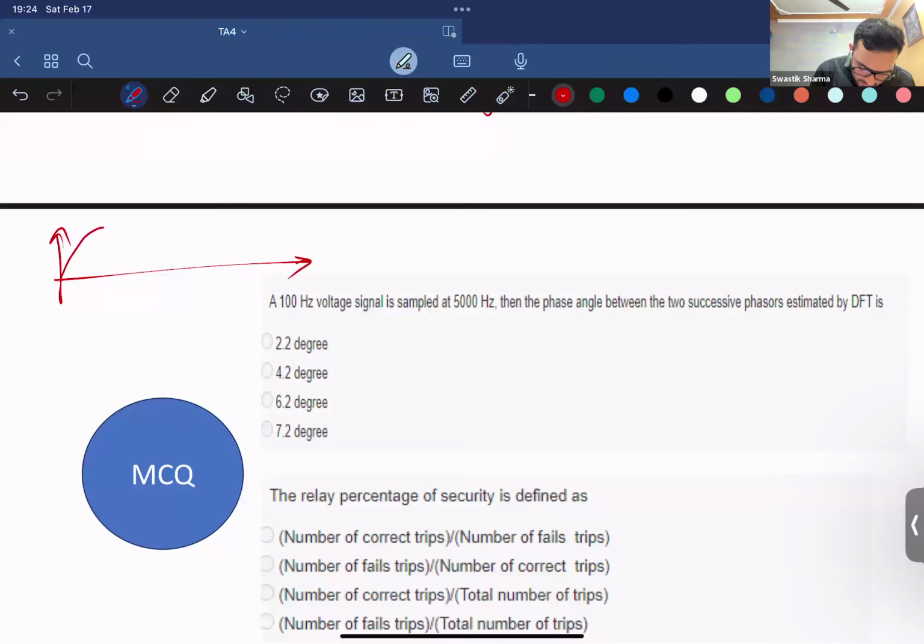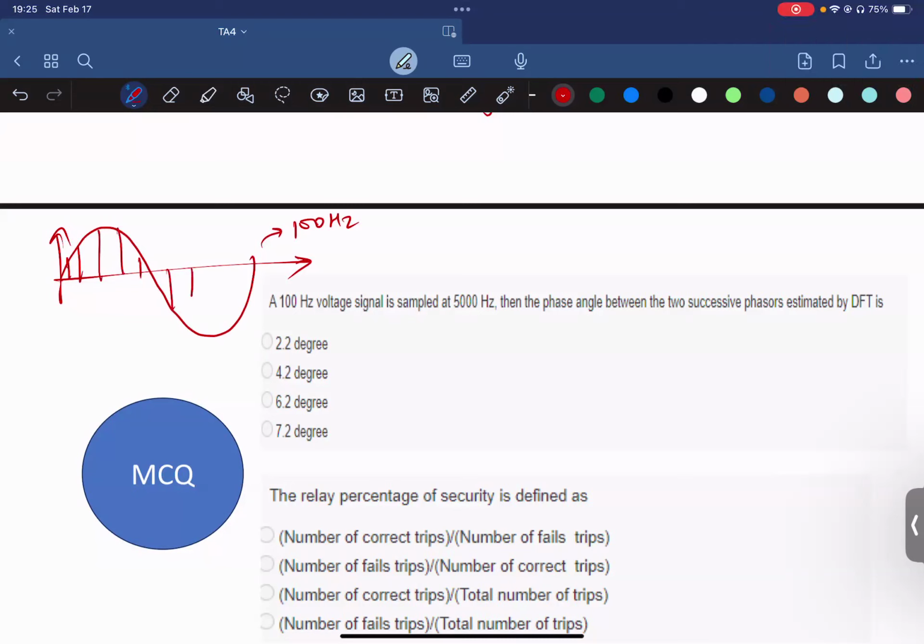So your signal is a 100 hertz signal and you are sampling it at 5 times the frequency, right? So let's say, okay, 7.2 degrees is the correct option. But to have everyone on the same page, let me tell you how it comes. So when you're sampling it at different samples, each of your phasors that are estimated...